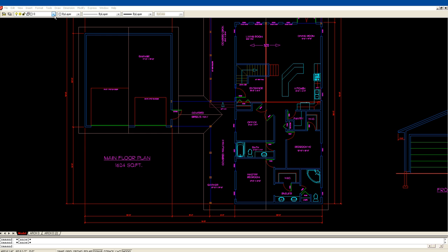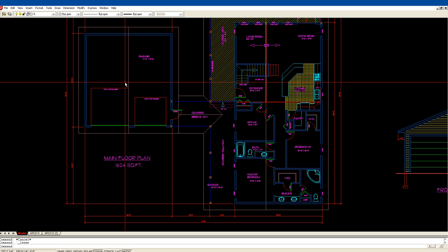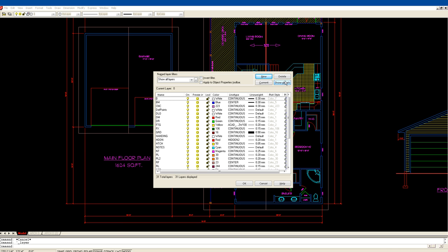Okay, so all the way through, you've been hopefully working off of my drawing, if you've been following along. If you've been doing any drawing, or you come in and download the basic drawing, you've had layers that are already attached, okay? I've kept my layers very simple, pretty self-explanatory what they're for. PL is point loads, roof, railing, stair, so on and so forth. They're all on. Well, we turned hatch off, so now we've turned hatch back on through the layer dialog box.